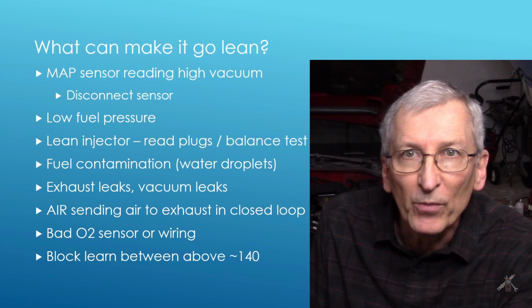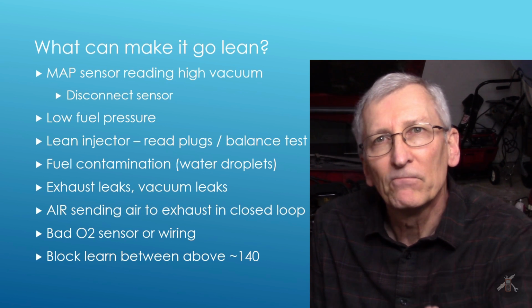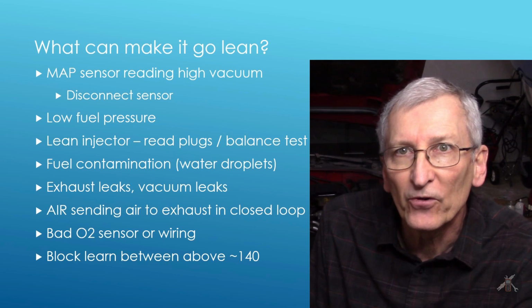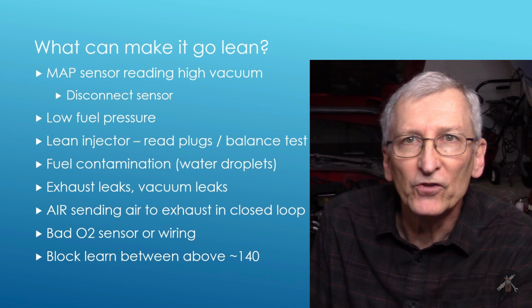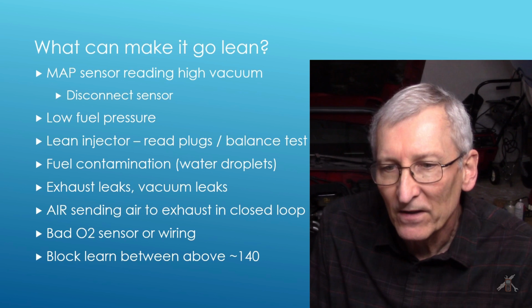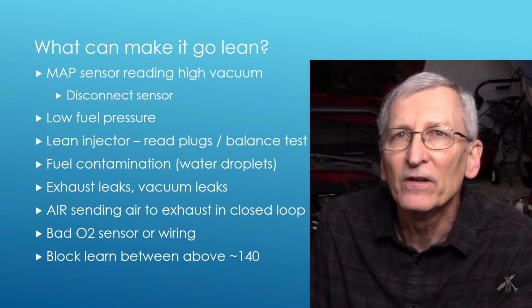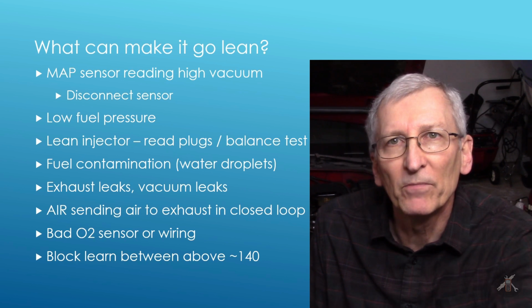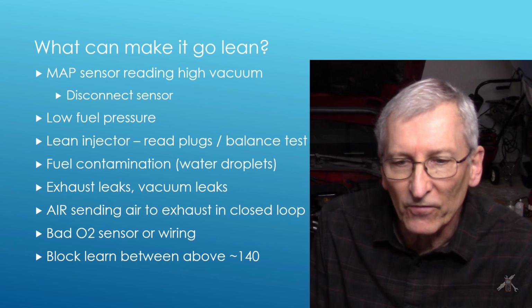Now, newer ones, OBD2 engines, with a V8 typically have 4 sensors. It's 2 on the engine, 1 on each bank, and then 2 behind the catalysts, 1 on each bank, because you need catalyst efficiency. Sometimes you'll see just 3 because they'll have a Y pipe and you'll only have 3 sensors, but that's a different deal.